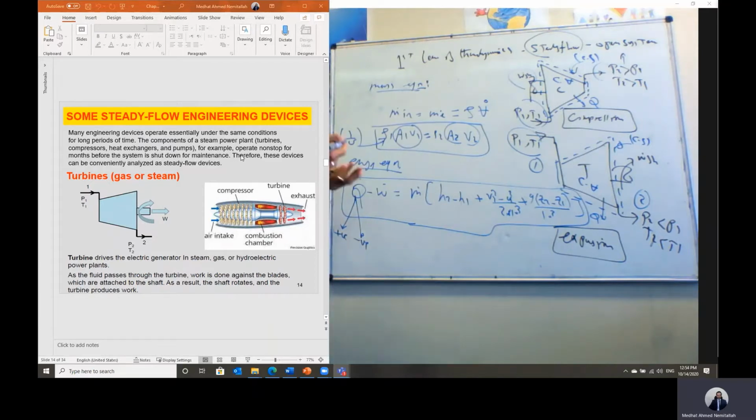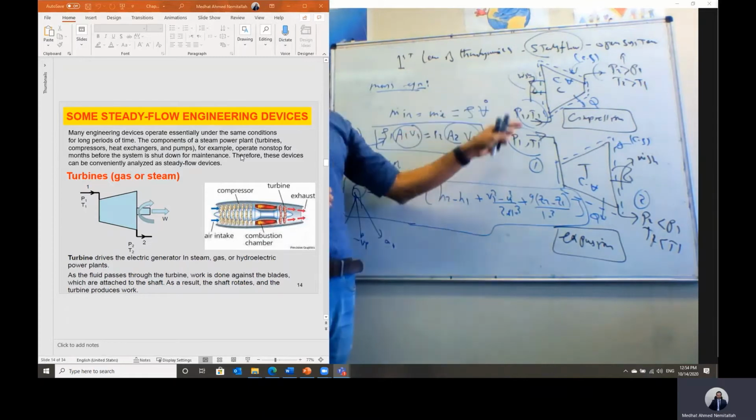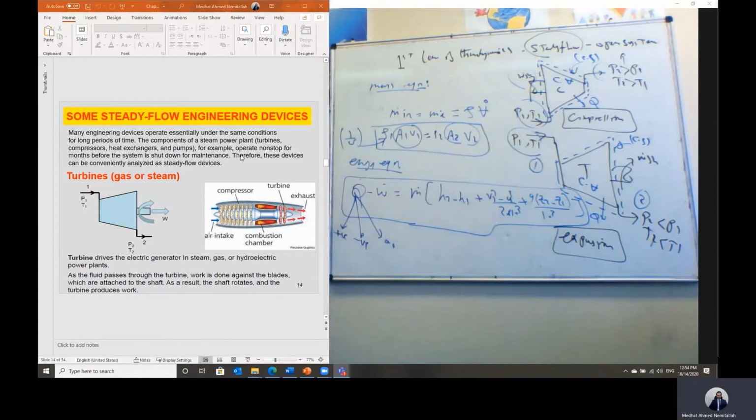If it says some heat is added to the system, then you consider it a positive sign. It could be adiabatic, insulated, or isolated, or in most cases for a steam turbine or compressor, he will not mention the heat transfer. So if it is not given or required, we can consider it as 0, as we explained earlier.